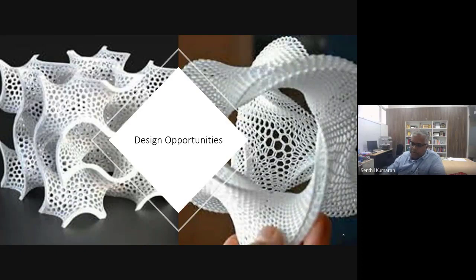We also had software that works on voxel-based FEM, the finite element method, and we simulated the mechanical behavior. We looked at it as a diffusion-type problem. As the bone started to grow, the scaffold got resorbed into the body and excreted out. We tried to understand the Young's modulus gain of the bone versus the Young's modulus loss of the scaffold, and it took 100 days.